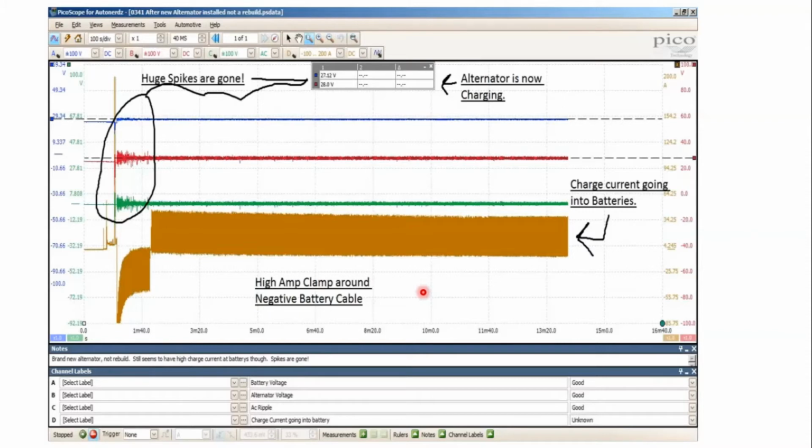So the alternator is going to be working overtime, trying to charge up those batteries, because it also sees a drop in voltage, and it overloads the alternator because of the extra current and the extra heat. The extra heat overheats your rectifying diodes in your alternator.